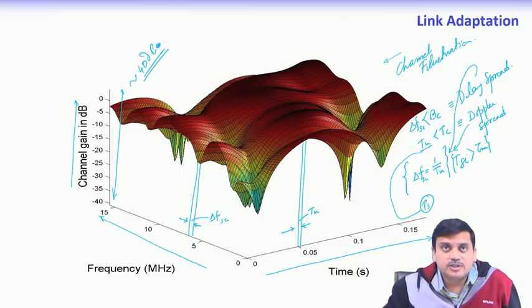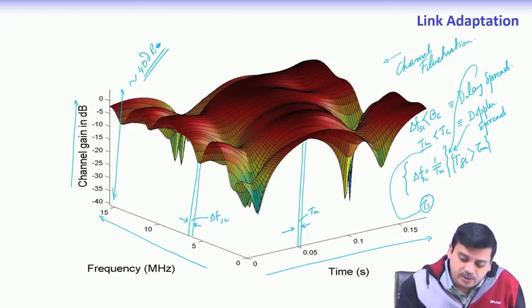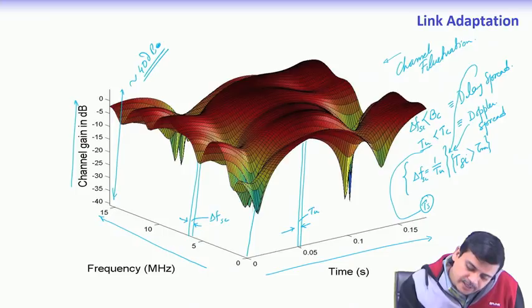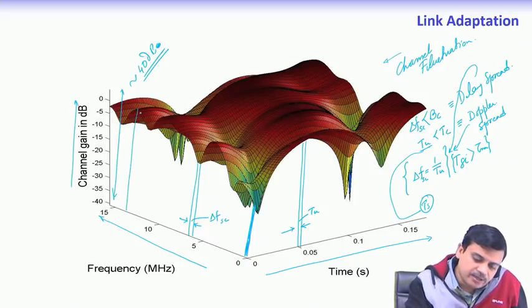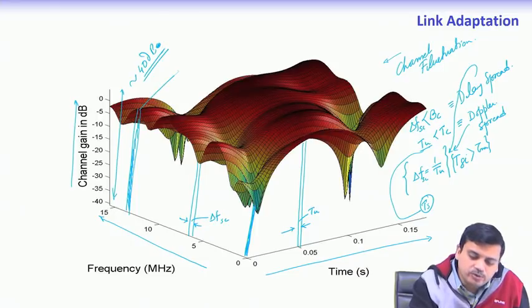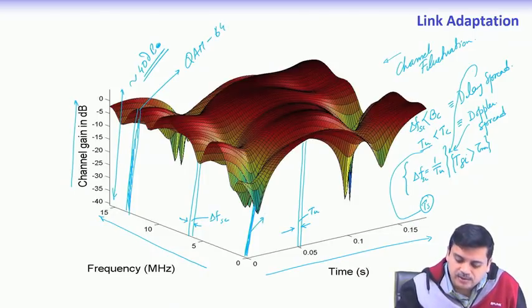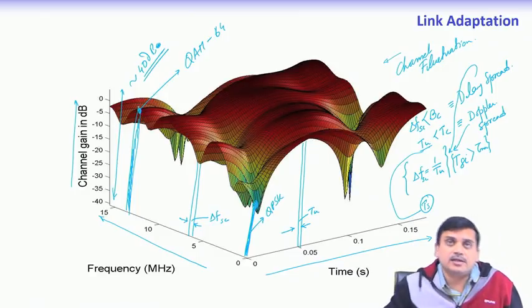So, in this situation, OFDM gives us the opportunity to allow certain subcarriers, for example here, which are facing low SNR conditions, and certain subcarriers here which are facing high SNR conditions, to use different modulation orders. So, let us say this is using 64 QAM and this is using, let us say, QPSK, because this is in lower SNR condition, this is at a higher SNR condition, right.